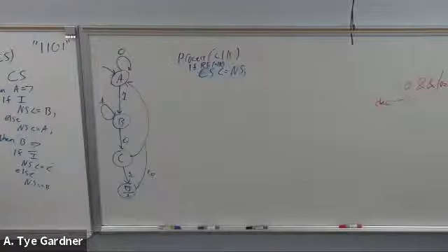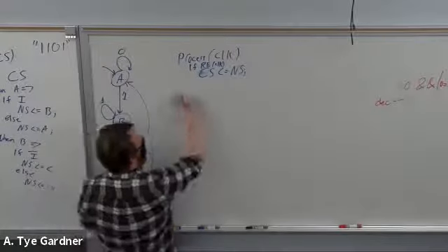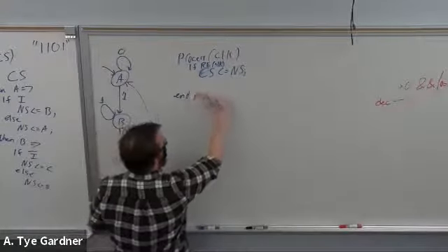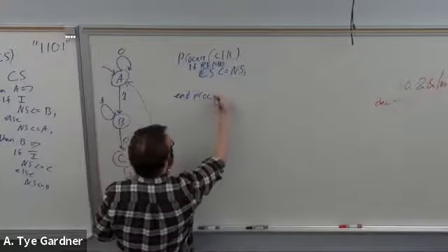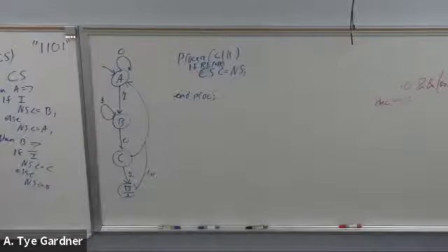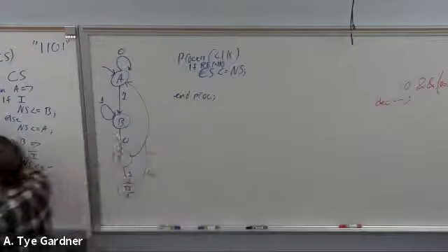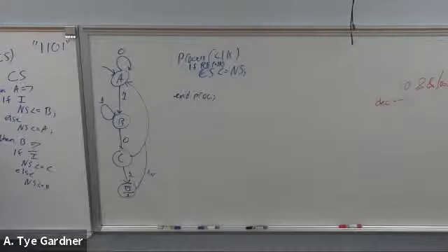Now the output decoder, it only cares about the current state because I said I'm making a Moore state machine, right? So the output decoder is, well, there's an end process here. There's an end process here. So outside of any processes, I'm going to stick to strictly combinational that just says my output, let's call it F, just for ease.